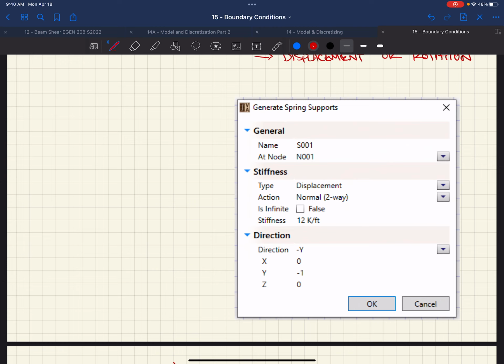generally, in design, there's some very strict guidelines, and your ability to manipulate what's right and wrong is harder for steel than it is for getting the loads in the first place, right? ASCE 7 tells us, if we're looking at an exitway, it's 100 pounds per square foot. Can't really get around that, right? But now you're like, okay, I gotta take that loading and I need to figure out what the reaction is at the base of this building, and there's a big gap, right?